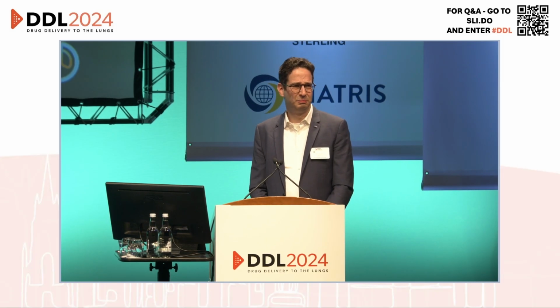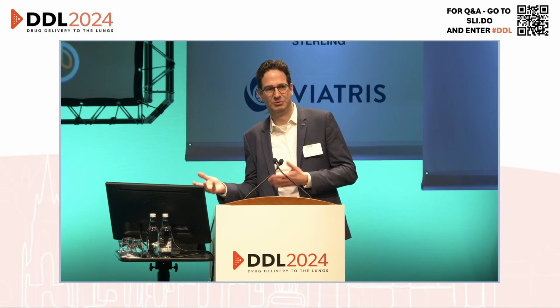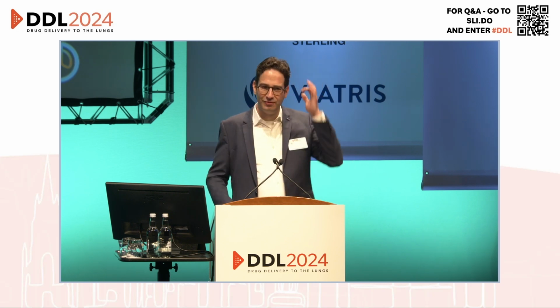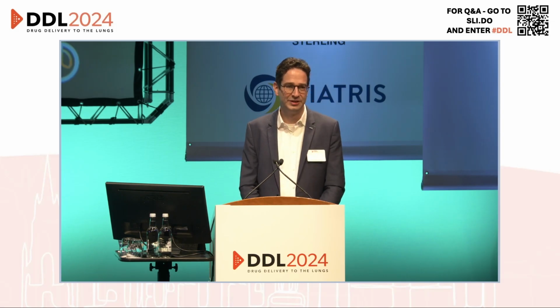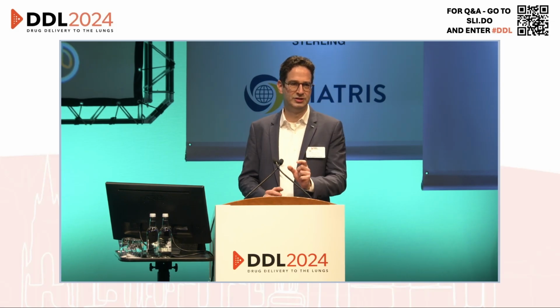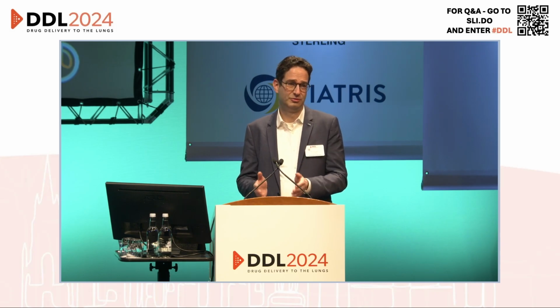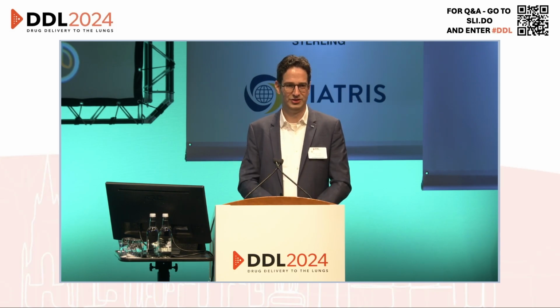Well, yeah, you can start to play around with the pressure. That's something we also experimented with. Problem is, if you want higher pressure, you need a stronger spring. So the actuation force increases, which is not always good for the user. And the other part is you have all these plastic components. They have to handle a larger force, so you might have to redesign those. So indeed, the range where we can play with it is limited. But as we are only changing the design of the nozzle, it's just a very small change to the whole device.